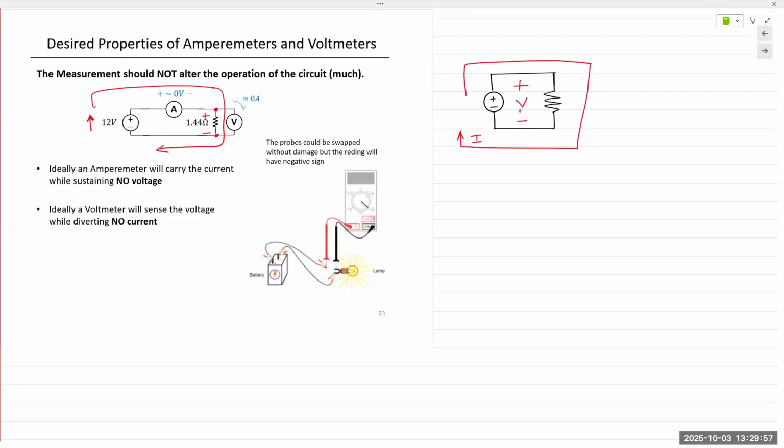If you want to measure V, we simply connect the voltmeter in parallel to that resistance. You're measuring the voltage. Positive terminal of the meter goes to the positive terminal of that voltage, negative to the negative, and you obtain a positive value. If we just randomly connected our voltmeter, the meter will still measure the magnitude. If it's 5 volts, it will show 5 volts, but it'll have a minus in front, so it'll show you -5. That simply means we connected the polarity opposite to what it actually is.